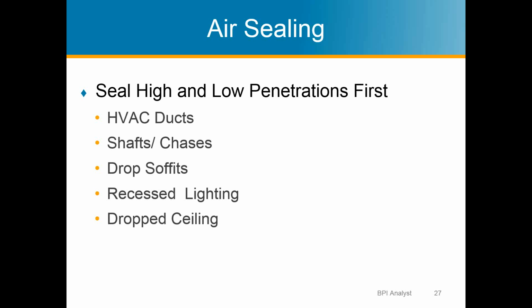And again, there could be wind, and wind alters the stack effect. So the neutral pressure plane has less meaning, but there's all these forces acting at once, and it's still going to have less value in the middle of the house than it is at the top or the bottom. Most of the time when I air seal houses, though, you kind of seal what's easiest first, and then work your way down until you run out of time or money or both. And you also can learn what's the best bang for your buck.